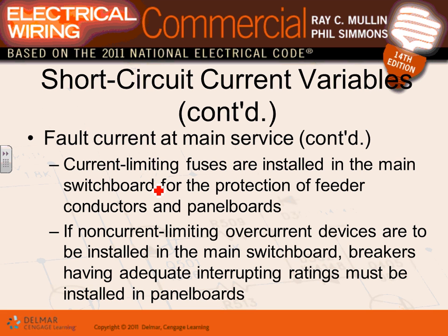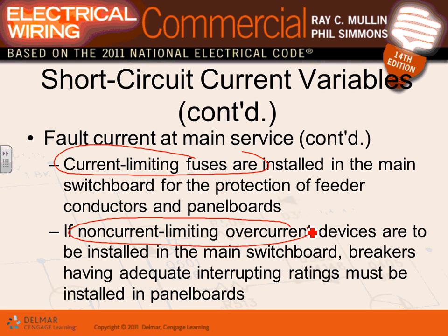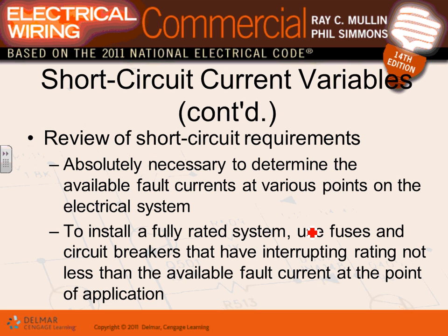There's also, for this project, they installed current limiting fuses, guys. Current limiting fuses, like I said, will limit the amount of energy upon the existence of a short circuit. Who cares? Your equipment will not burn as much. So they're installing non-current limiting fuses downstream and current limiting fuses in the main switchgear. If you have current limiting fuses, you will limit the energy, not just interrupt the fault.